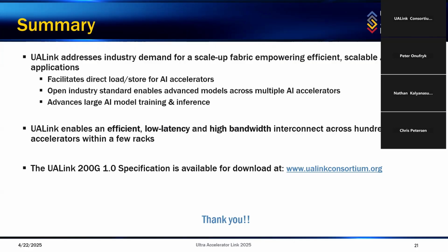It's also focused on low latency. In this particular case, really all of it has been architected to be able to get through the various layers of the stack as efficiently as possible. And because it is ID routed, it also allows the switch implementation to be very straightforward and simple. It allows us to implement a non-blocking crossbar, and the packets can do a very simple lookup on the switch side, which prevents any need for very large buffering, and there's no challenges with head-of-line blocking. Again, ultimately resulting in low latency and consistent low latency.